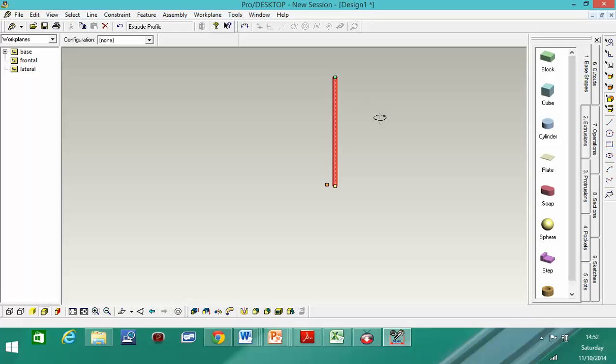Okay, we'll be learning this as we're moving along, so there's absolutely no point of sitting here and going through the whole project while you're still learning. So I will be taking you step by step. So the first step is to create this cylinder, starting with a 2D circle, extrude.